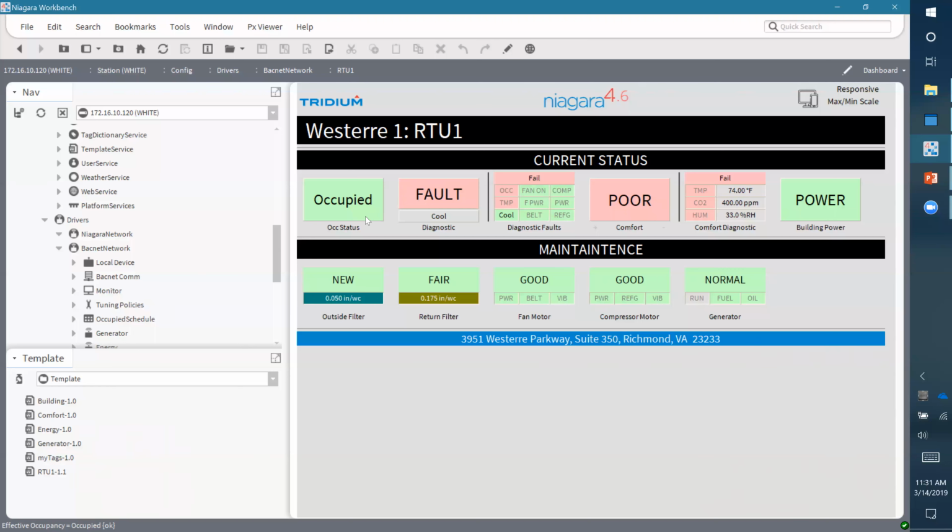Let's see. When you add a BACnet device, will it write the device ID to the controller when it is being added? If you noticed, when I deployed the template, I used that dev tool, and it automatically did all that work for me. So I never had to enter that in or match it. It just happened in the discovery process. I like to leverage that dev mode because I don't have to go back and rematch any of my devices.